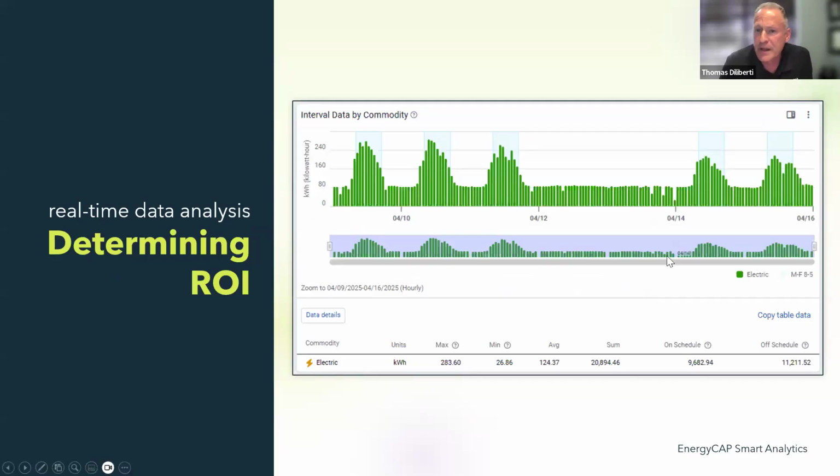Here's another great example. In this situation here, what you're looking at is a different chart, and this is showing a 7-day week. So what we've got here is we've got these humps. So this would represent a Wednesday, a Thursday, a Friday, and then you've got Saturday and Sunday, which is suggesting the buildings are turning off because this data is kWh data. Okay, should have probably said that up front. So we're looking at the usage, the kWh consumption of a building. This suggests that there are no humps on Saturday and Sunday. And once again, the building turns on and runs on a Monday and Tuesday.